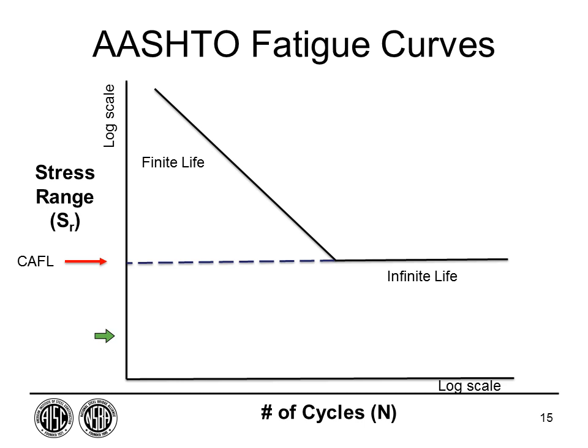If you think about that, a bridge structure is going to be probably out there for 75 years. If we think we can forecast what kind of loads and number of cycles it might have, generally you should design for infinite life. But there are cases where it could be prohibitive, where you would say, well, I'm going to design for finite life, maybe on a temporary structure, for example.